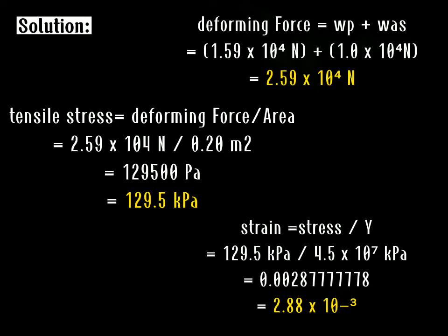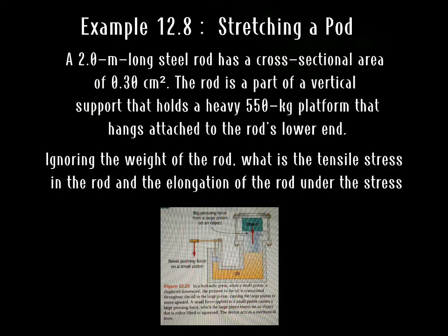So, the normal force acting on the pillar's cross-sectional area is not constant along its length, but varies from its smallest value at the top to its greatest value at the bottom. As a result, if the pillar has a constant cross-sectional area along its length, the stress is greatest at the base.